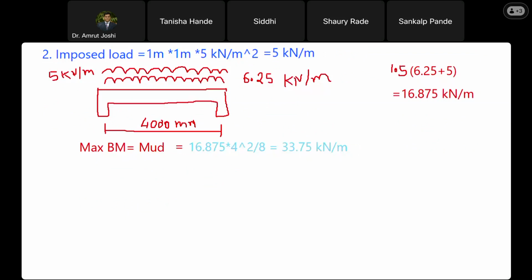And what is the shear force? So design shear force. For which shear force should I be designing this slab? I should be designing this slab for the shear force prevalent at distance d from the face of the support. We did this last time, didn't we? Yes, sir. The crack will propagate at 45 degrees.